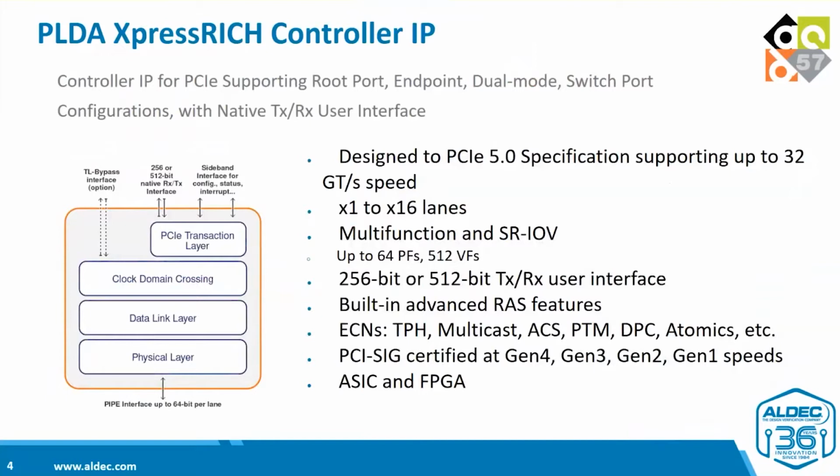Coming to the features of the PLDA XpressRICH controller IP. This IP supports all the modes, from root port, endpoint, dual mode, and switch port, with native interface. It is designed to the PCIe 5.0 specification, supporting up to 32 GT/s, and configurable as x1 to x16 lanes.